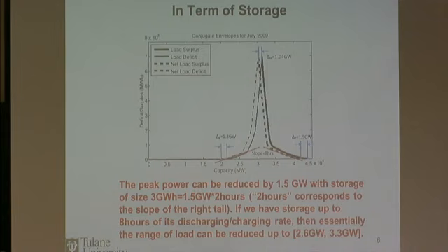However, the negative impact of wind is that at night, you eat into this base load. At night, you really don't want to have very low demand, because that is the time when very often you have negative prices. You have a nuclear plant running, and you don't really want to mess with that part. It's really very fixed.